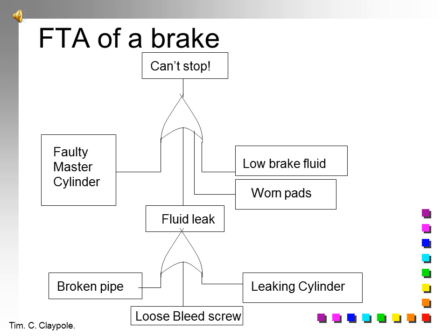For the fluid leak to occur, you can have a broken pipe, you could have a loose bleed screw, or a leaking cylinder. So these are all OR situations. Any of those that occurs, you get a fluid leak. Because you've got a fluid leak, you can't stop.